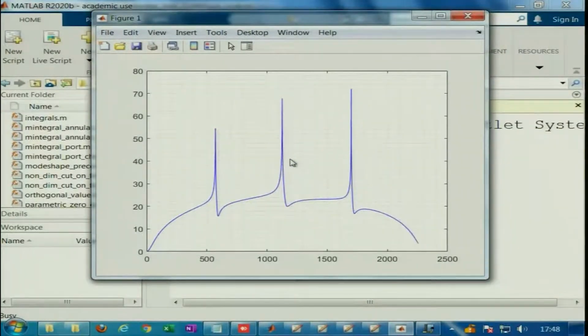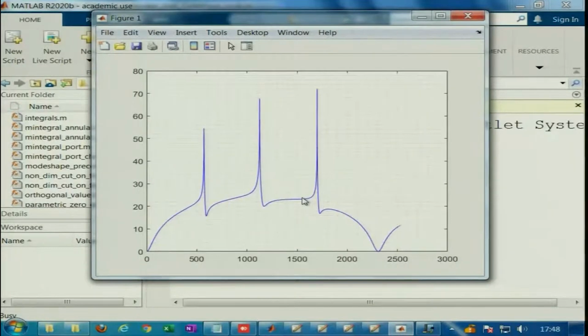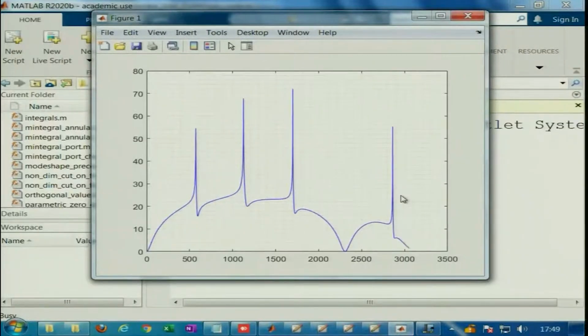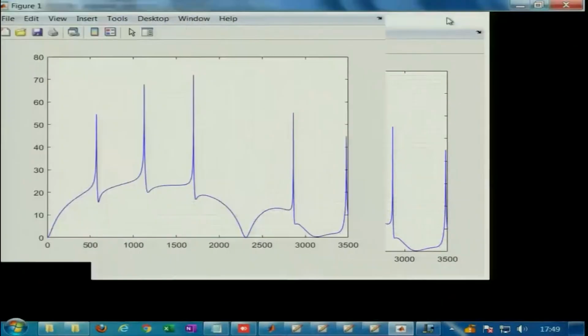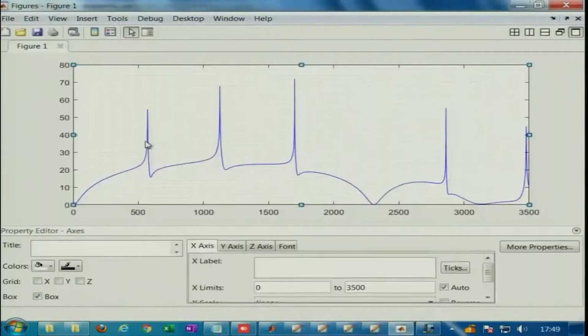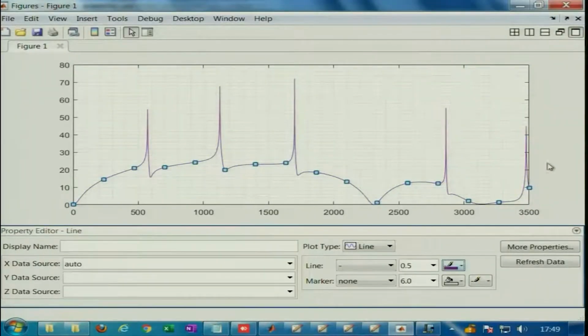This should have been more towards the right hand side, and this is really because the thickness effect has not been considered in the last case. The tuning lengths were obtained without due consideration of the finite thickness, which is very important in all practical applications. So, the end correction formula that was developed by Chaitanya and Munjal several years back, they did a whole lot of parametric studies in a commercial software to evaluate the transmission loss performance of extended inlet and outlet muffler, incorporating the wall thickness effect of the inlet and outlet pipe, and they figured out that this is what happens, and they developed an empirical relation which we can discuss just in a while. I can just present to you that expression, and now this curve is ready, and I guess I should probably change the color, let me use another color, perhaps this. Okay.